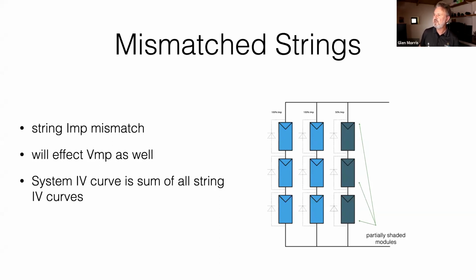Those bypass diodes, are they the same as optimizers, asks Mishra. No, optimizers is a kind of industry term. More technically, in Australian and New Zealand standards, we refer to them as DC conditioning units. So anything that modifies the voltage, current, and power of the input to the output is a DC conditioning unit. And products like SolarEdge, Tigo, Huawei make products that do this.